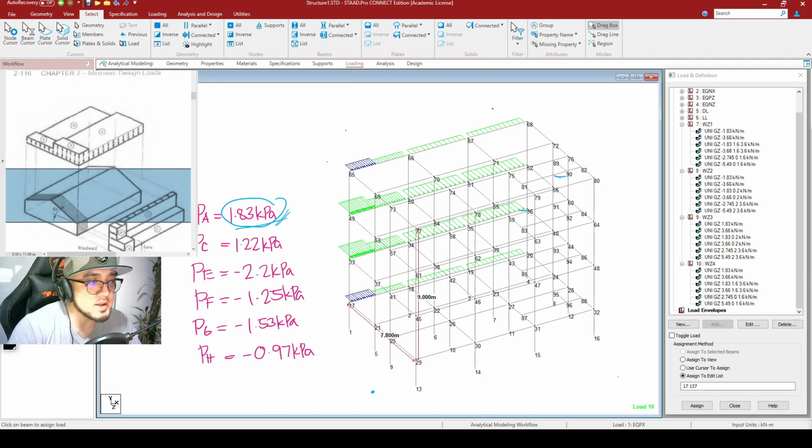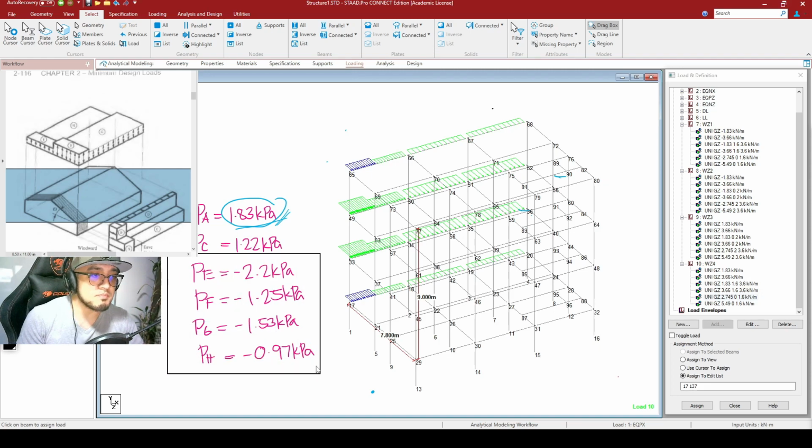But as you can see guys, these pressures right here are negative. Meaning that these particular pressures are suction in nature, or suction pressure. So if they are to be vertical pressures, they would be acting vertically upwards because they are, I'm sorry for the term, practically sucking the top portion of our building. I can't think of a better term, or vacuuming or whatsoever. So that is to be the case.